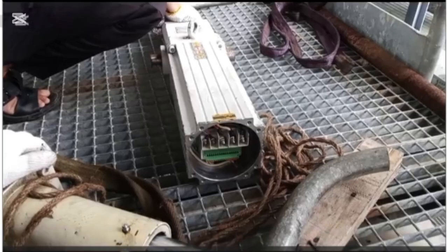In the field we found that the actuator is not properly opening, and from our server we applied different signals, but the IGV is not working properly. That means it is not opening and also not closing. So we took a decision to interchange the driver unit of the IGV. And in our store there is a new IGV unit.